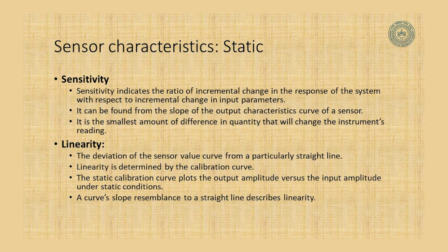Can it measure 1 degree change? Can it measure 0.5 degrees change? Can it measure 0.1 degrees change? Okay. So, when you are selecting your sensor, then you have to think about the sensitivity as well. Okay. Is my sensor going to be sensitive enough for the type of physical measurement that I am going to do? The next characteristic is that of linearity.